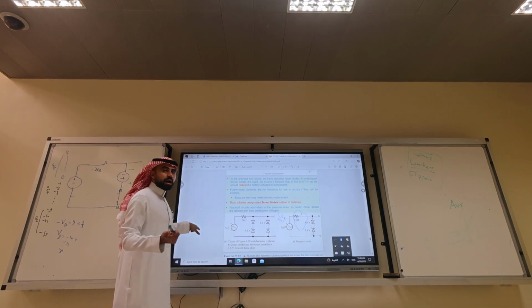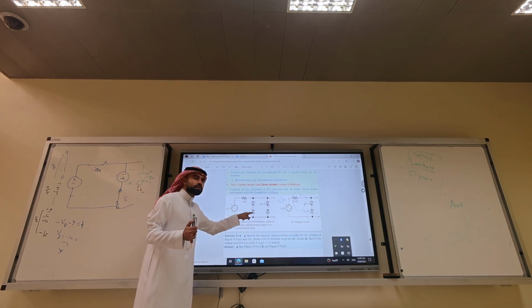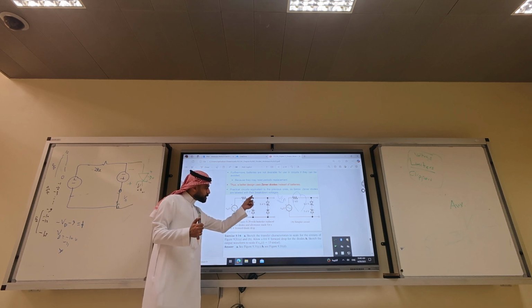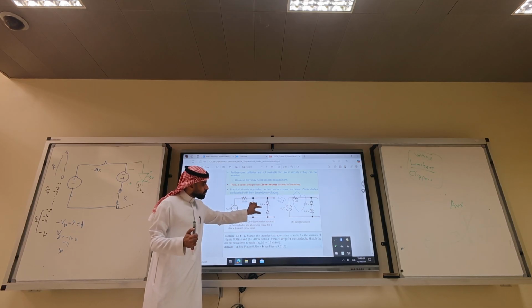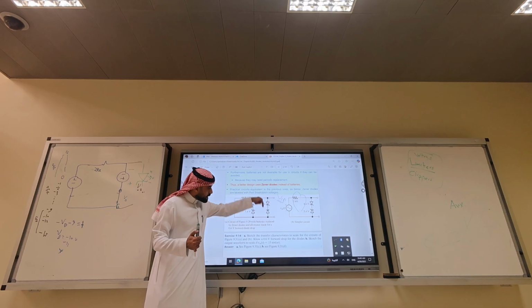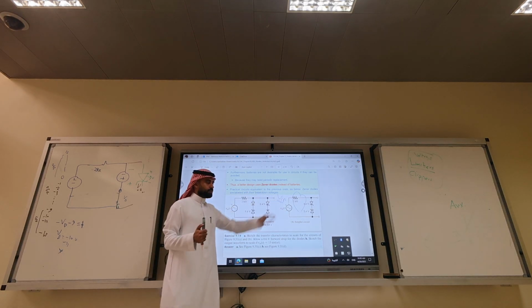Then what did we say? We want to save more money. We can't put batteries in the chargers. Then what do we put? Zener diode. And why did we add 5.4? Because we assumed the 0.6 model here. 5.4 plus 0.6 will give you 6 volts. 8.4 plus 0.6 gives us 9. This is minus 8.4 minus 0.6, which will be minus 9 volt output.